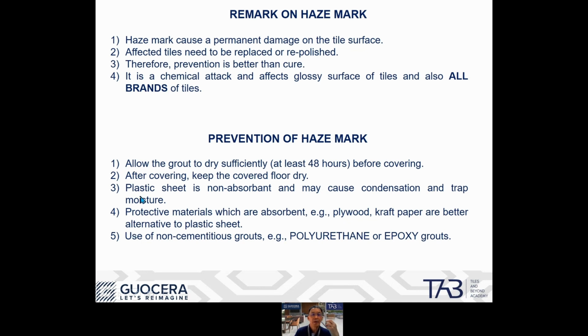Now, to talk a bit about plastic sheet. Plastic sheet is a non-absorbent material, and even on certain hot days you can find condensation, and this condensation can also cause very slight haze mark. Of course, there are alternatives to plastic sheet: protective sheets which are more absorbent, for example plywood, or materials like kraft paper.